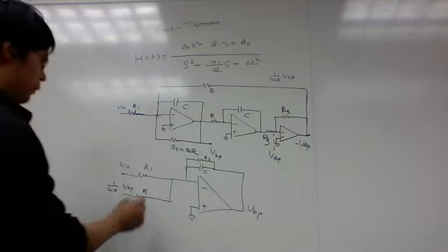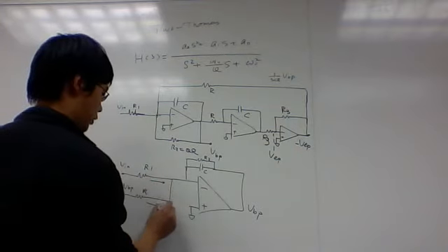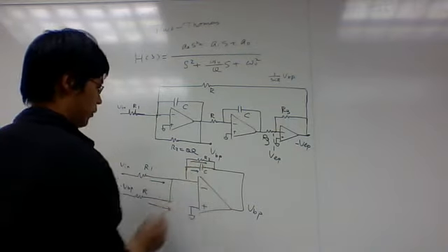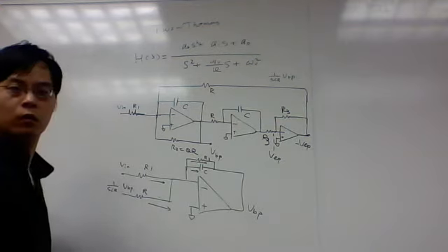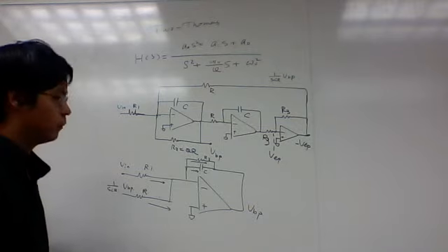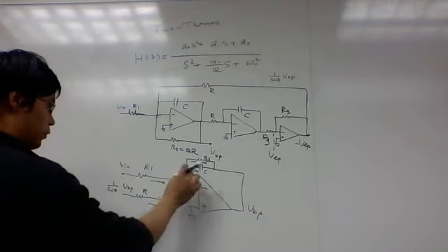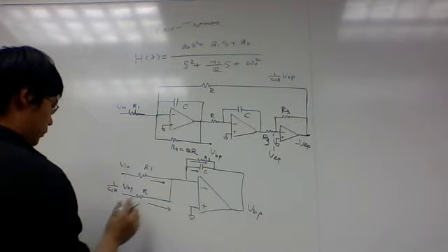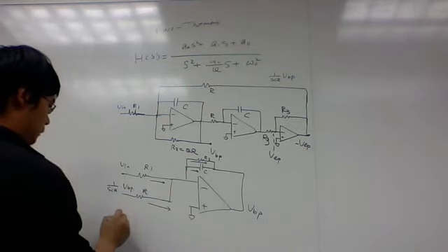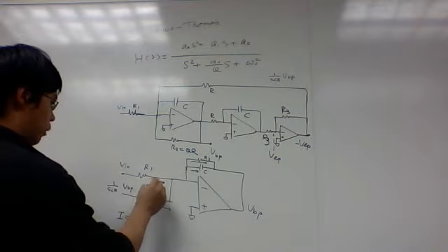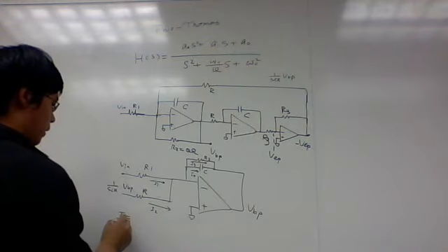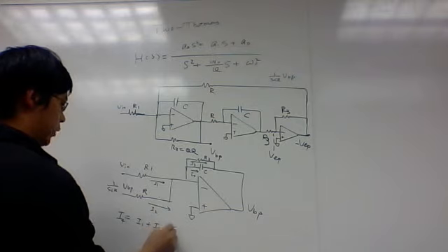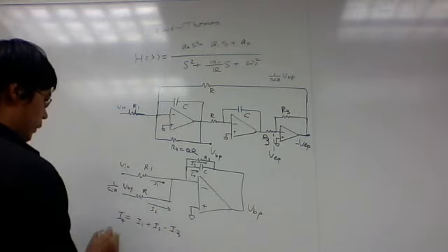So basically you have a bunch of currents, right? So this current, this current, this current, this current. Okay. So focusing on this current, say I1, I2, I3, I4, right? So I4 will be equal to I1 plus I2 minus I3, right? So I4 is what?